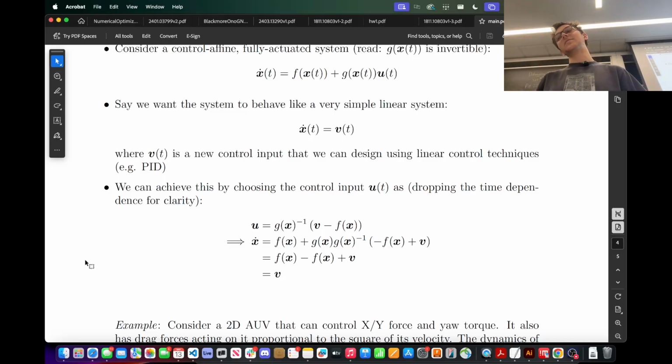Most basic example: a flat sheet in water moving broadside has a lot more surface area and a lot more drag than my vehicle moving forward. So anytime you significantly change the geometry, you want to know about it. But the most important things are mass, and if you add a lot of weight on the outside of the vehicle, the inertia.